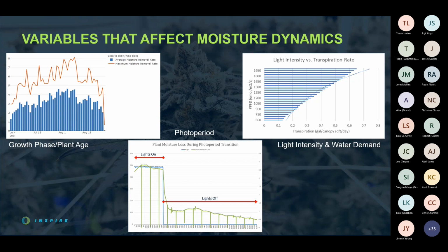As the lights turn off, the temperature drops and the relative humidity spikes, which requires an immediate and significant dehumidification requirement. This spike can be overcome, again, with things like variable capacity systems, appropriately sized reheat, and purpose-built controls, which are things that come standard in Inspire's units.